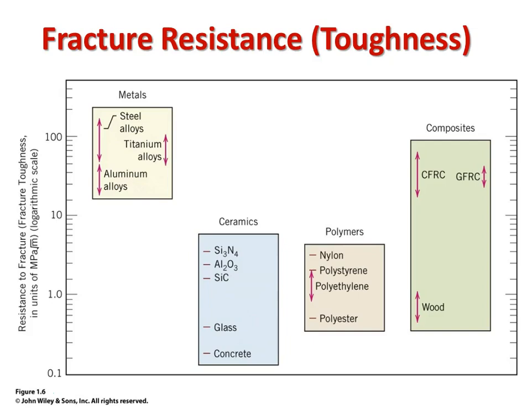Polymers are the opposite. They tend to have very low strength, but tend to have high ductility, but nonetheless the combination is low. So if you need to impart a lot of energy, especially in a short amount of time, ceramics are definitely not your best choice, and polymers can be problematic. And again, if you need the best of both in terms of lightweighting and fracture resistance, composites are a good choice, but unlike strength and stiffness, they still lag your more common engineered metals by within an order of magnitude. Speaking of order of magnitude, again, we've got a bigger spread. Not as big as stiffness, but definitely bigger than density and tensile, looking like 3 orders of magnitude.